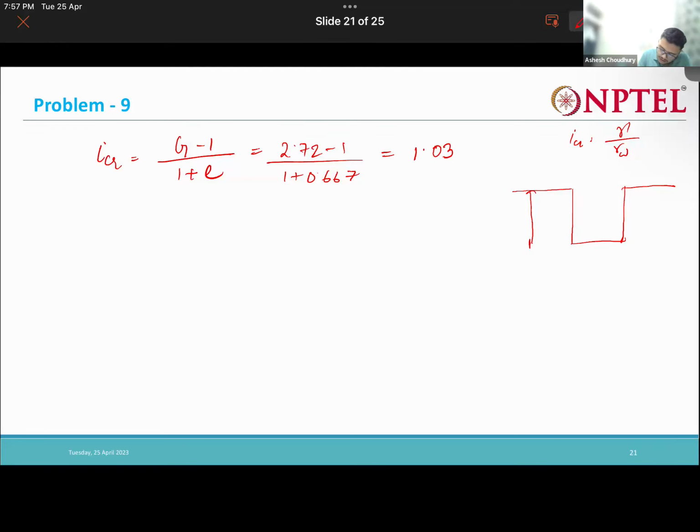Okay. So let us go to the next part. This problem is from the chapter of consolidation. A 1 meter thick layer of saturated clay, drained at both faces, settles by 15 centimeter in 2 years. If a thin layer of pervious soil is introduced in the middle of the layer, then what will be the period during which the settlement of 15 centimeter will be completed?